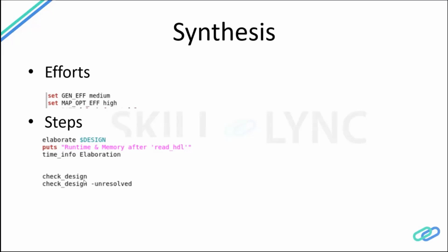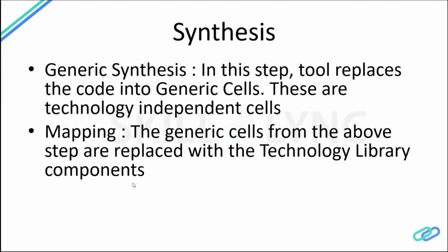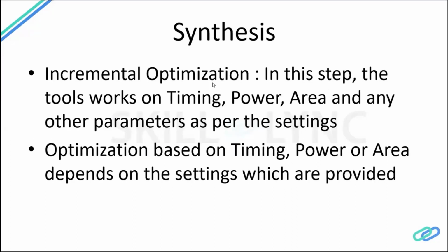Check design, check design unresolved. It will list out every component which is not matching the required spec. Then it will do the generic synthesis, the mapping stage, then incremental optimization.